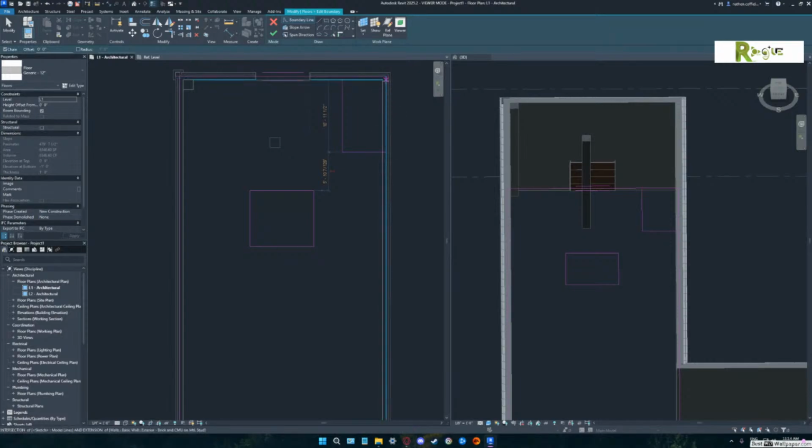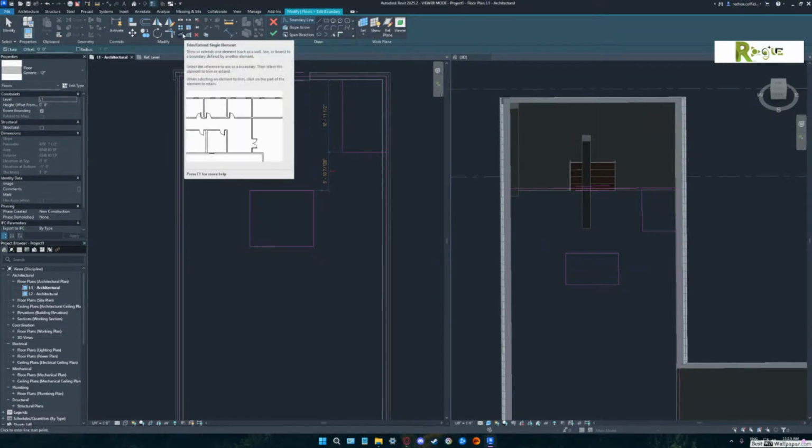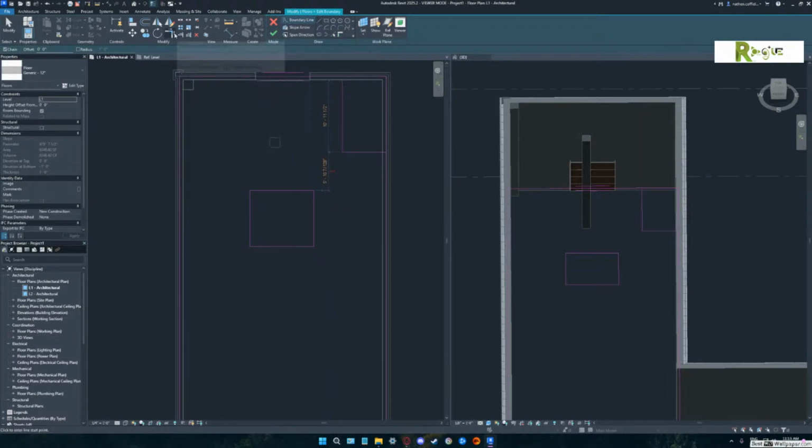So have you done the trim command yet? I think so. Yep. It's the one with the two that go into the 90. Right beside that, to the left. Nope, the other way. There you go. And then just trim the two sticks that you don't need anymore. So click below that, and then go to the wall. Go below the wall.